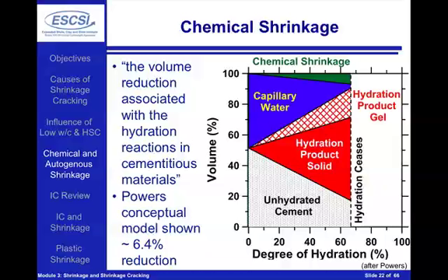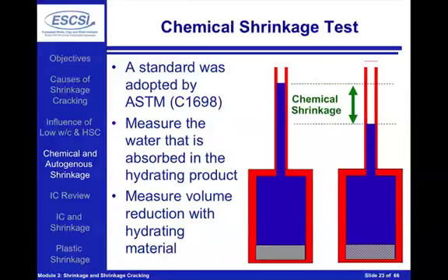When we start to talk about supplementary cementitious materials, the chemical shrinkage goes up. For a C fly ash or a slag, we may see this number going as high as doubling. With other materials like silica fume, where we have the pozzolanic reaction, we can see this going up even higher, to 3 or 4 times the chemical shrinkage of Portland cement.